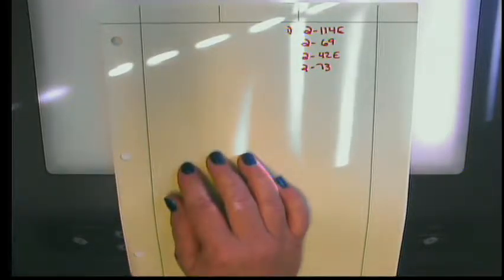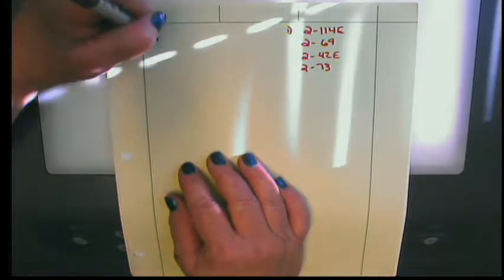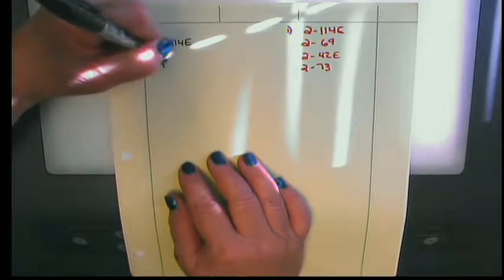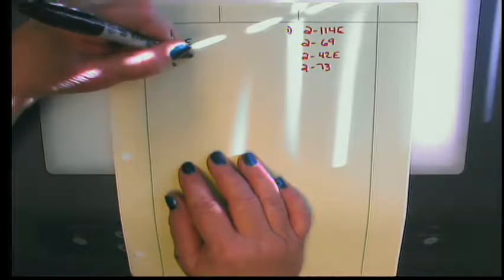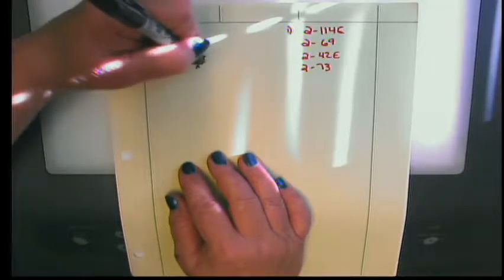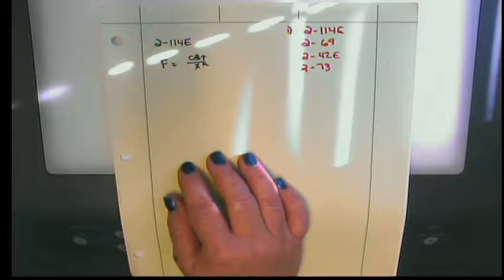114 says, the force required to compress the gas in a gas spring a distance x is given by this equation. And the equation for force is this constant divided by x, which would be the distance of compression raised to the k power, where the constant is determined by the geometry of this device and k is determined by the gas used.